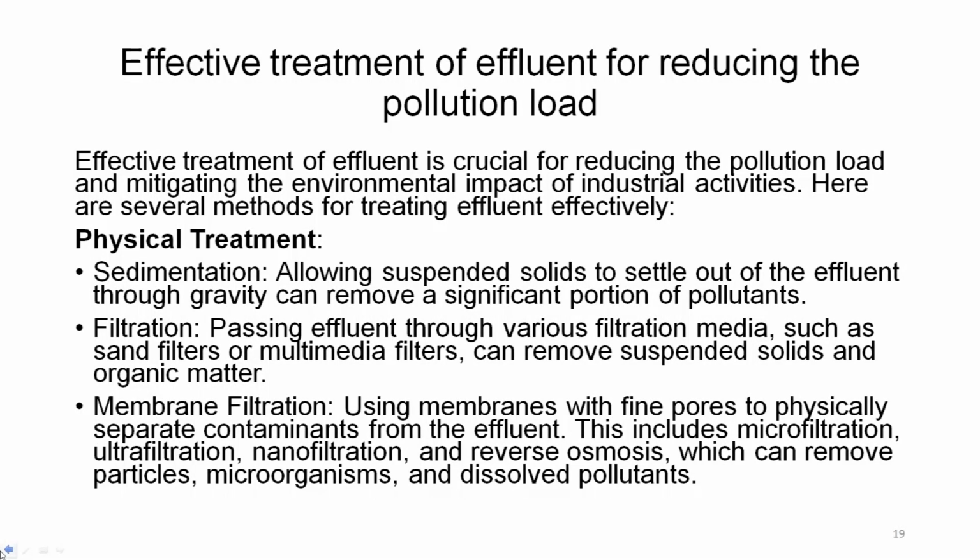Effective treatment of effluent is crucial for reducing the pollution load and mitigating the environmental impact of the industrial activities. Here are several methods for treating effluent effectively. Physical treatment: sedimentation, filtration, membrane filtration, etc. Sedimentation allows suspended solids to settle out of the effluent through gravity and can remove a significant portion of pollutants.